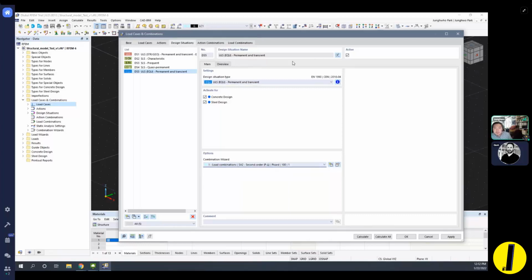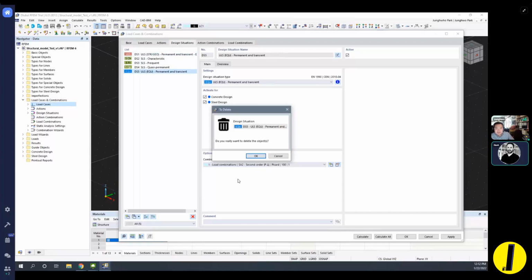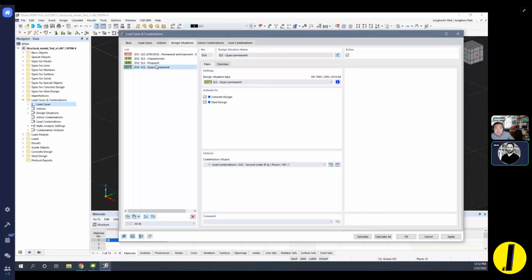But Goran, one moment, just for maybe some of the architects watching this. Do you know the difference between ULS and SLS? Can you shortly explain ULS and SLS? ULS and SLS are the two main points defined by Eurocode or norm: ultimate limit state and serviceability limit state.